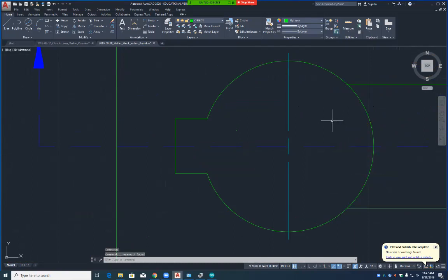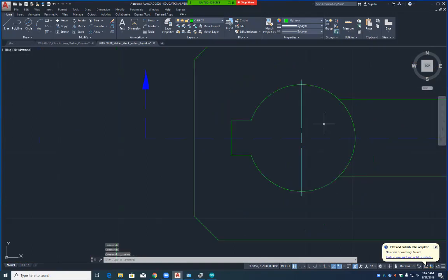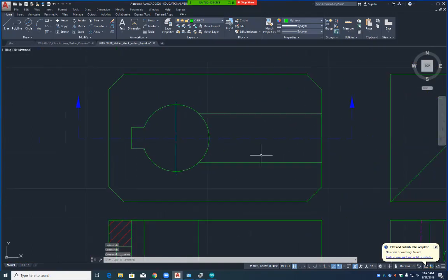Is this right or wrong? Did you explode the center line and then just delete the horizontals? You have to explode the center line in order to extend it to get a 1/4 of an inch, don't you? Yeah, I got up to 1/4 inch. Did you delete the horizontal of the center line then? Uh-huh. Okay, so something like that.